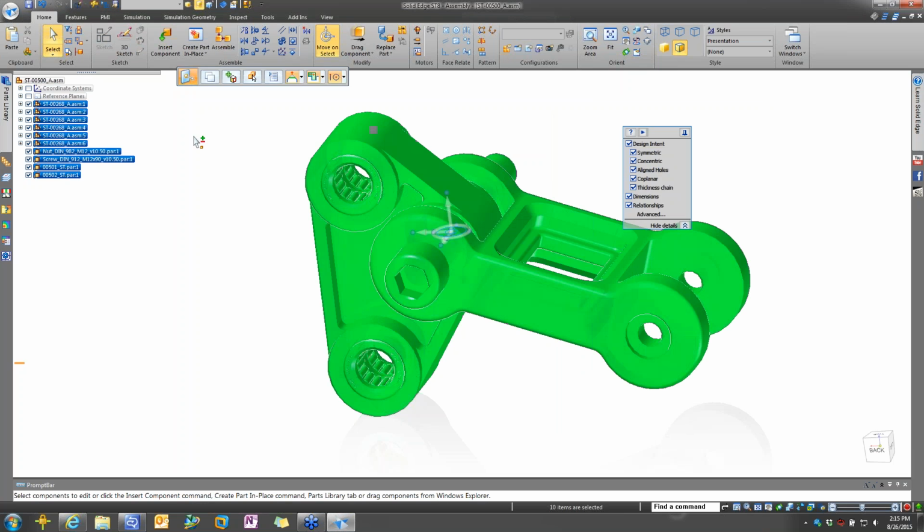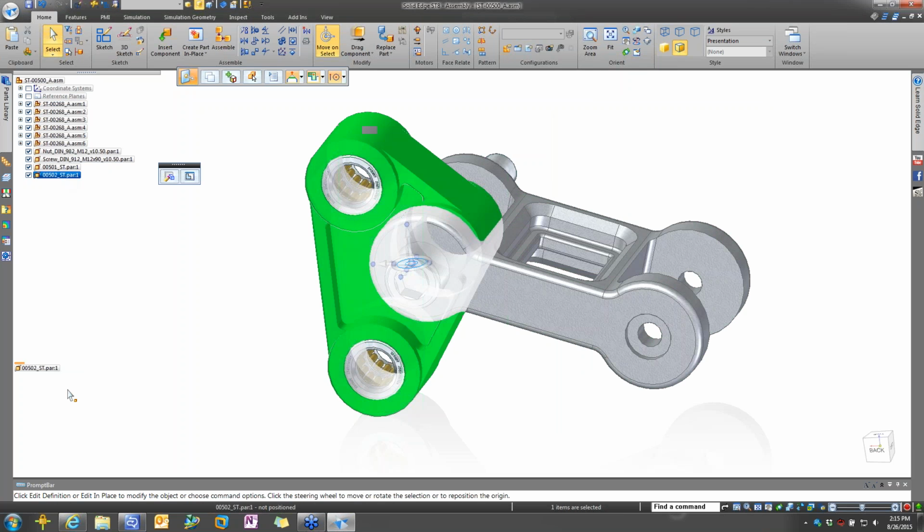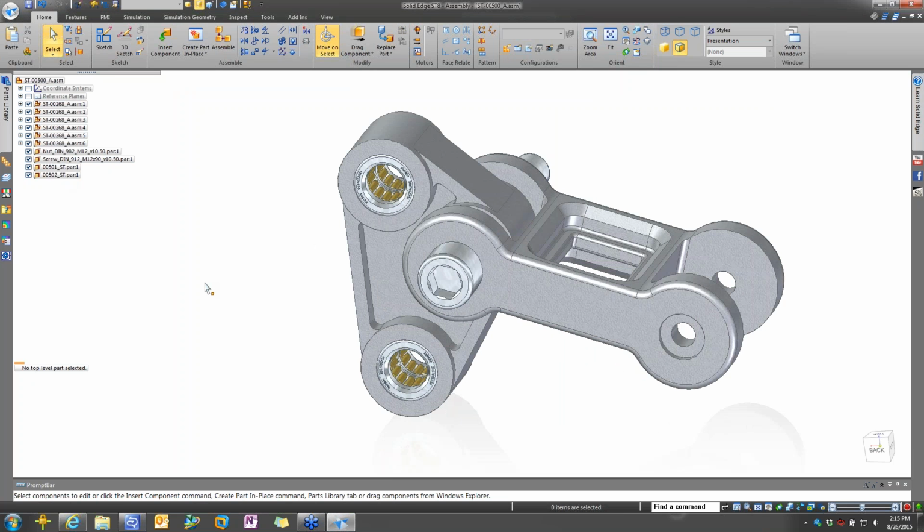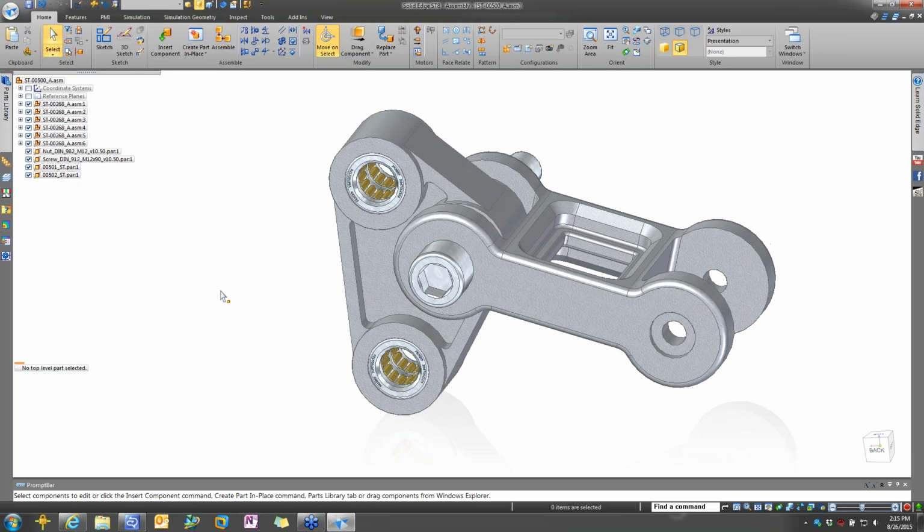And what you'll notice is as I select on any of those parts, that grounded relationship is now gone, and I've done that for each of those components all at the same time. And what I may want to do now is utilize that same tool to add that intelligence in automatically and save myself from the manual process that the other CAD systems out there on the market have to do, where they have to individually constrain those components one by one.